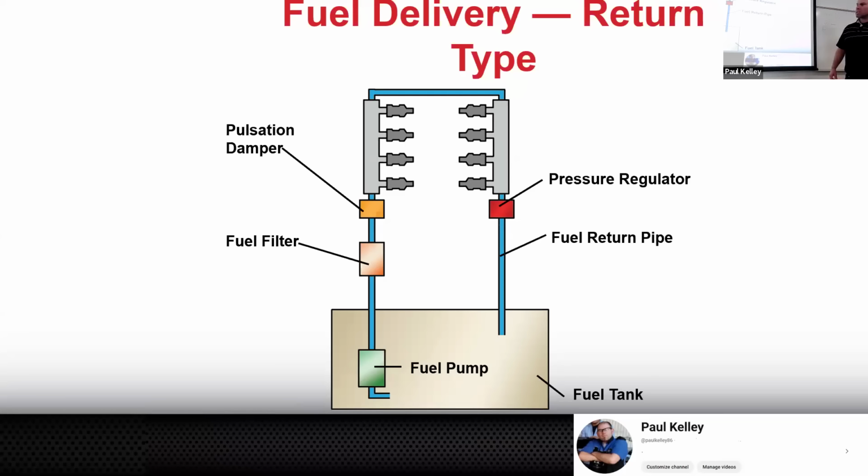The reason it's submerged in the tank is pumps don't like to have to suck really hard to pull fuel up. They do best when they push. So if we set the pump in the fuel, it's just getting fed with as much fuel as it possibly needs, and it can push it all rather than try to draw it all out. The pump's going to last longer. This is a much better design, much longer lasting for the fuel pump. Makes sense?